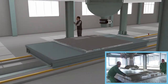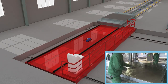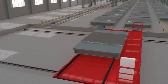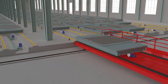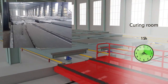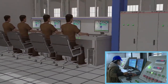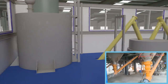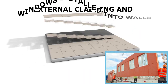When the foam process is finished and has gained a certain strength, spray a surface layer of nanometer cement. Then lay a layer of fiberglass mesh. When the surface of the semi-finished product is flat, send it to the curing room for 24 hours. Now, the product can be used.